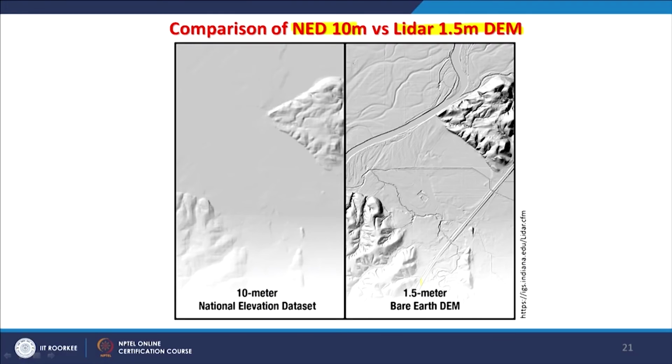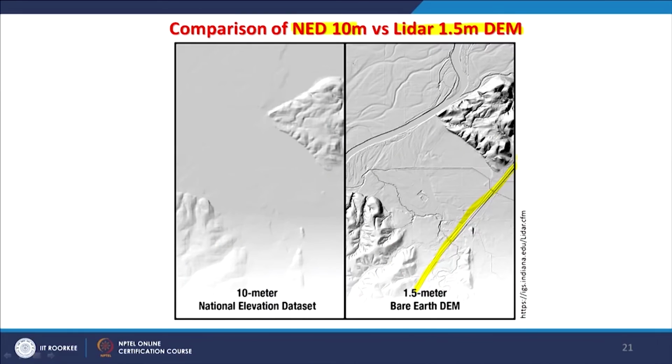However, as I have mentioned, it is very difficult to completely remove all surface features, man-made structures, or natural canopy from that surface. So, it is still not qualifying as a typical digital elevation model, but lies in between a DEM and a DSM. To some extent the surface features have been removed, but their remnants are still clearly visible in a very high resolution digital elevation model.